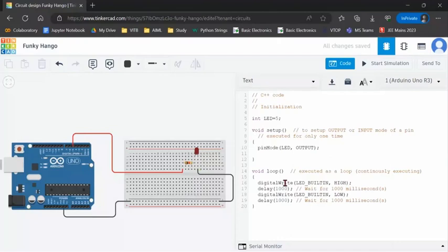So how will we provide it? How we should be writing is decided by the command digital write, because we are utilizing digital pins. Okay, so we'll be writing digital write here. Digital write is the code, and the first argument is the variable name. The variable name we have provided is LED, so we'll be writing LED. Initially it is 0, so we'll be making it high. Then we stop the command and provide some delay.